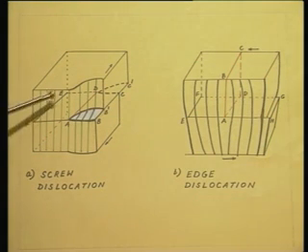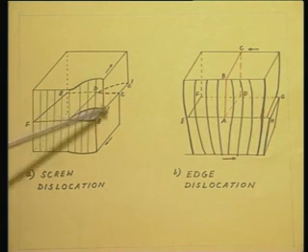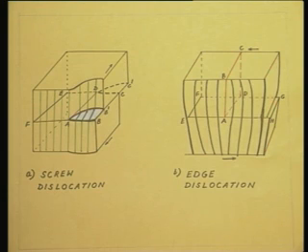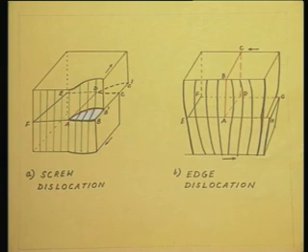You have deformed the crystal, and this line AD is the line of deformation. On the left of this line AD, I have a perfect crystal. On the right of this line AD, I have a dislocation. So, this is called a screw dislocation. Remember that this shear stress has to be in excess of the elastic limit. Within the elastic limit, the crystal will try to adjust itself. It is only when it exceeds the elastic limit that it gets dislocated.